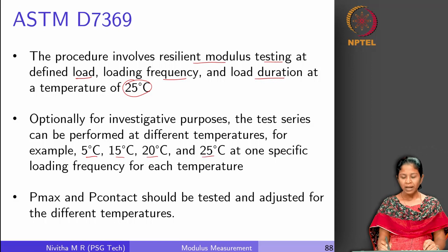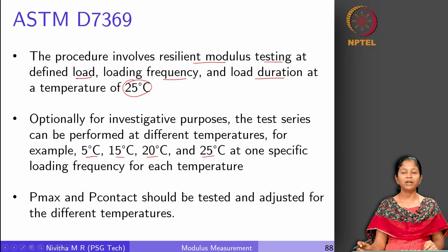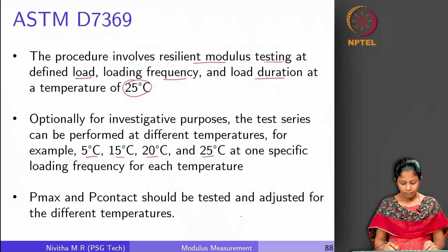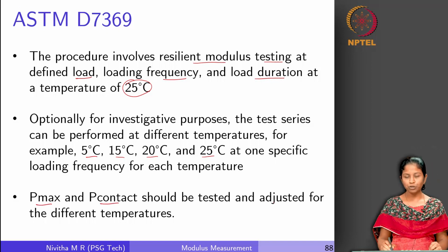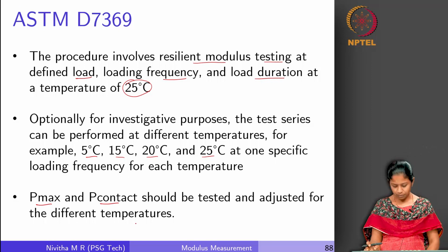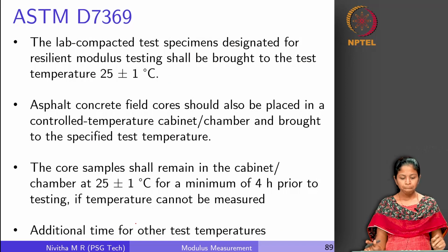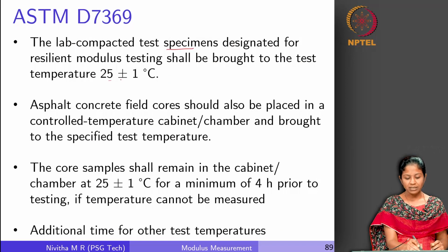And again it could be done at one specific loading frequency or different loading frequencies for a given temperature. For each case, the P max and P contact values should be tested and adjusted. So, that is the only thing that we have to do when we vary the test conditions from this particular standard condition. So, the lab compacted test specimen shall be brought to this test temperature.